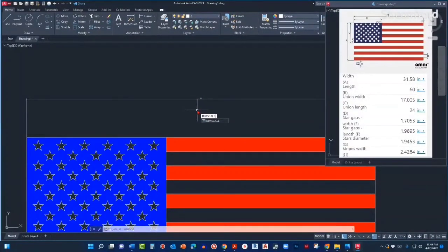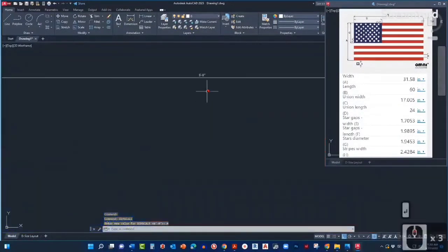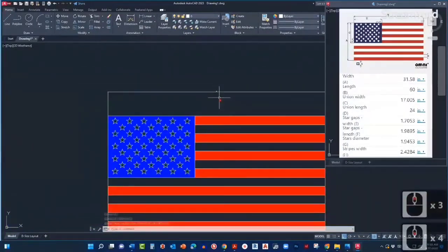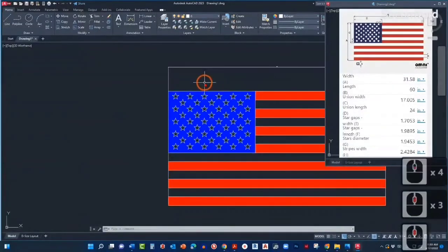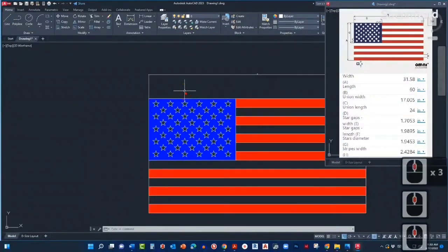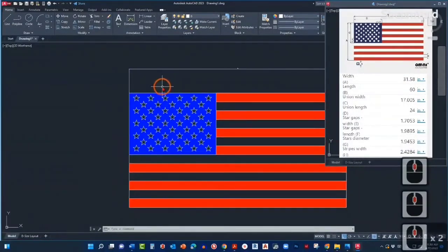And this is going to help us scale the dimensions automatically based on our viewport scale. In this case, we said it was 3 inches, right? And it was a factor of 4 based on our chart. So let's pick that and let's type 4 for our dim scale. So once we do that, we can see that nothing really happens. Our dimension is still tiny. Well, it's because we need to do another dimension to see the changes.